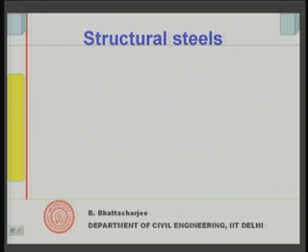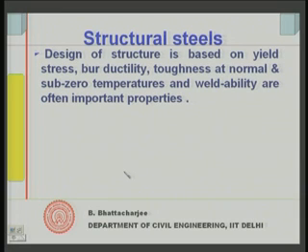Okay. Now, structural steel. By this time we have become aware that stability is a major criterion. Therefore, design of structure is based on yield stress, that is, the useful stress. Beyond that there is excessive deformation, so we do not use that stress. Yield stress is the useful stress for our purpose of design.